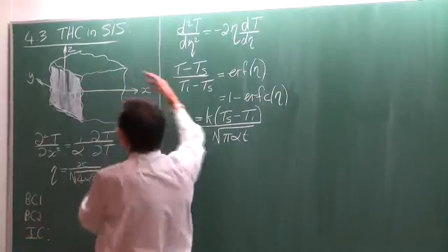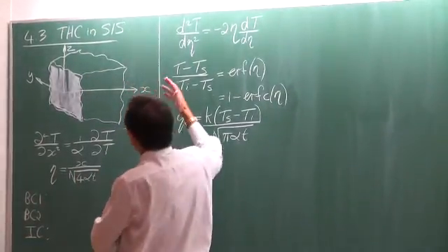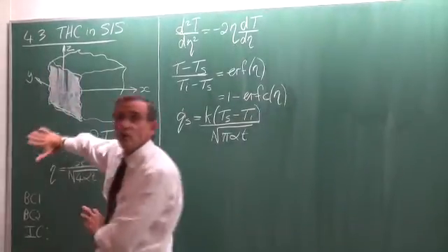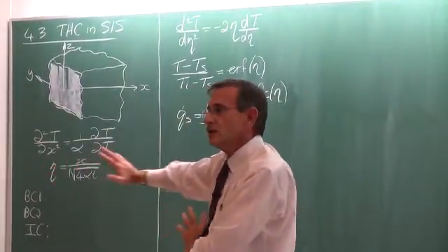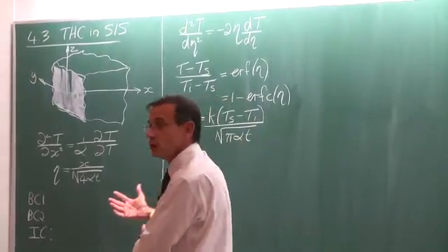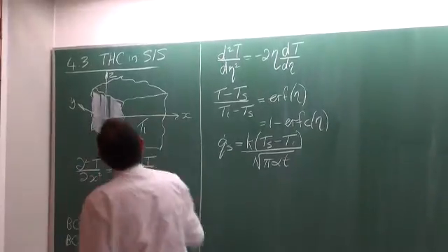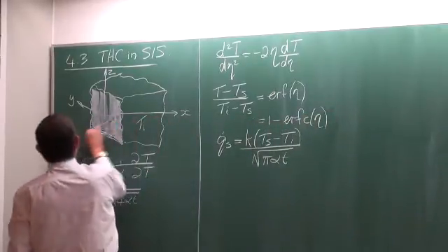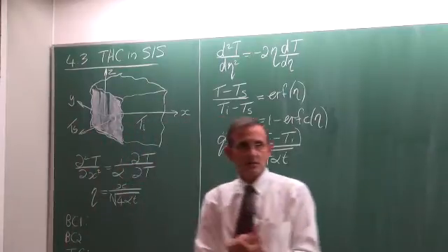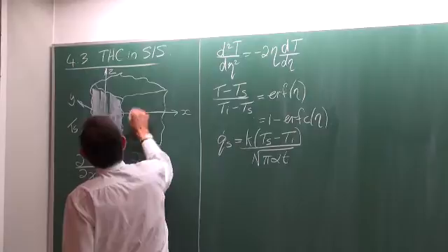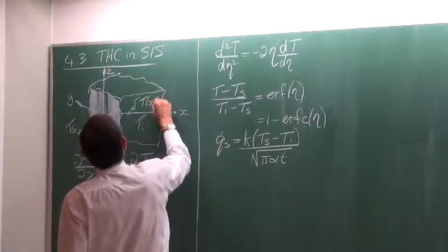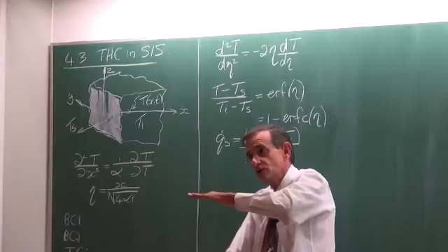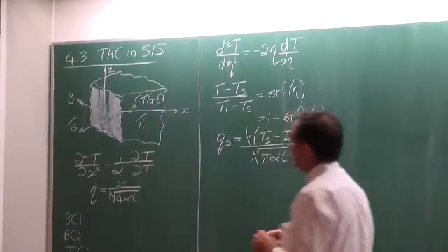Okay. So this can be the Earth, can be a semi-infinite solid, but a very important characteristic of a semi-infinite solid is that it must have a surface. And on that surface, things will be known, or there will be certain boundary conditions. In this case, the semi-infinite solid, like the Earth, is at a constant temperature, and then suddenly the temperature here changes to maybe Ts. And then we would like to know the temperature anywhere as a function of x as we go deeper only, not in the y direction or the z direction. We would like to know how the temperature behaves.